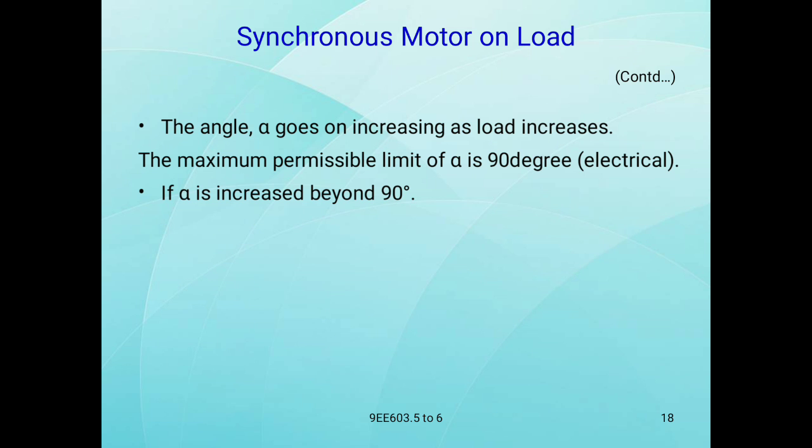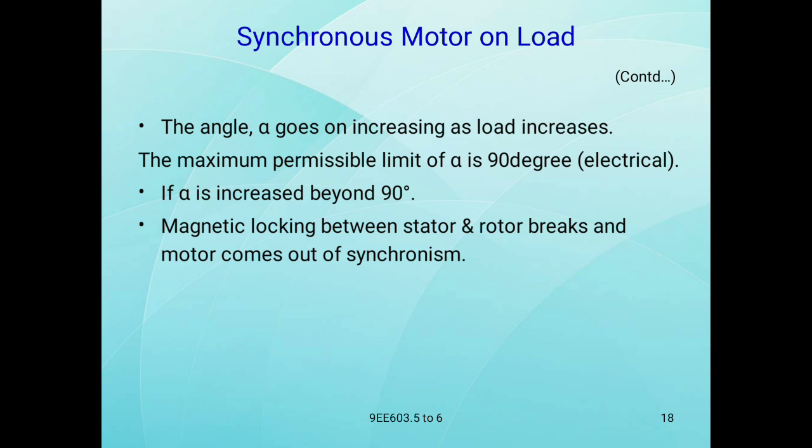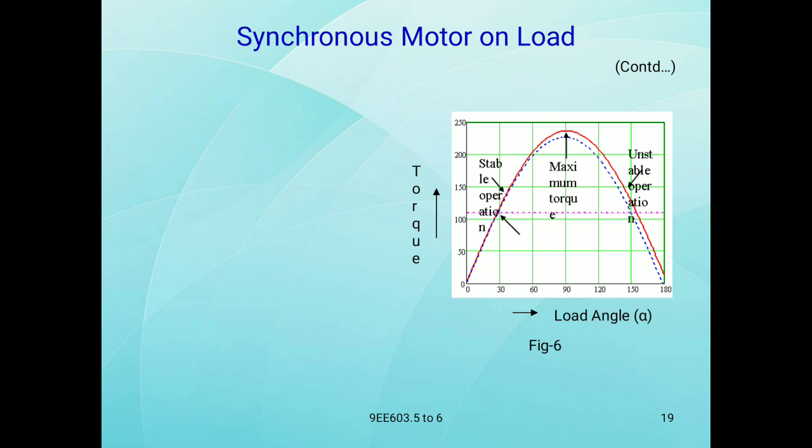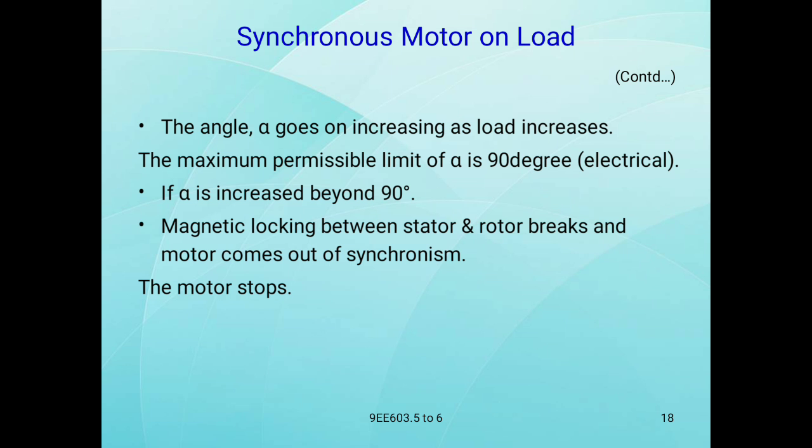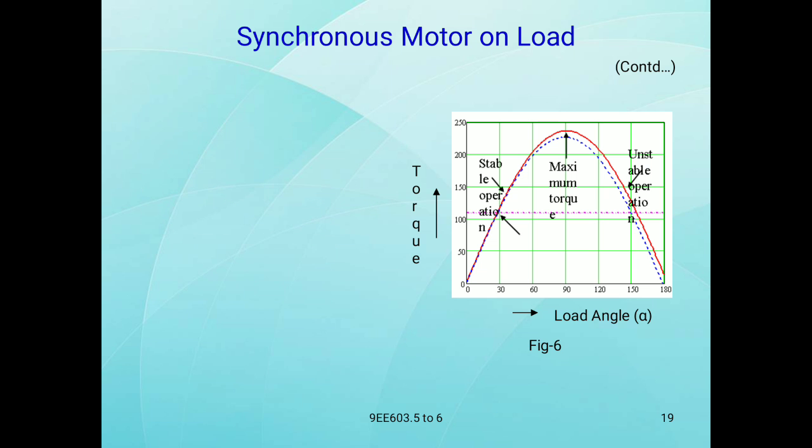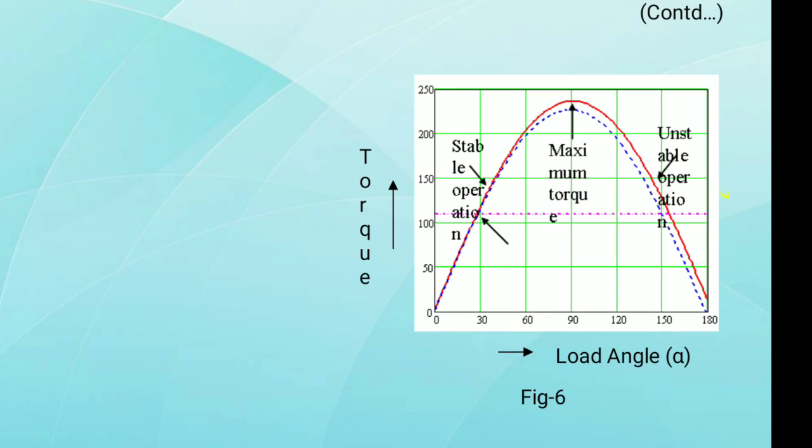If alpha is increased beyond 90 degrees, the magnetic locking between stator and rotor breaks and the motor comes out of synchronism. The motor stops.